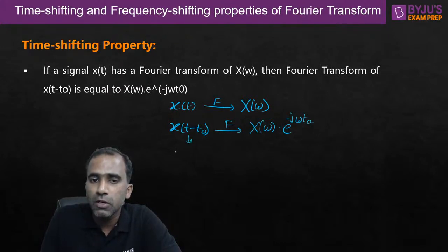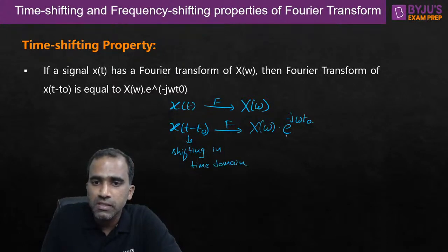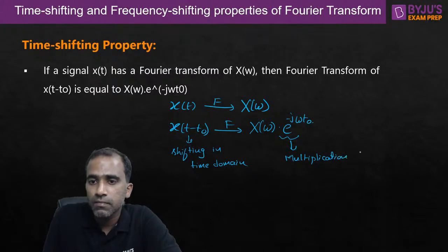So shifting in one domain, or time domain, what will that do in frequency domain? Shifting in time domain results in multiplication with a complex sinusoidal signal.